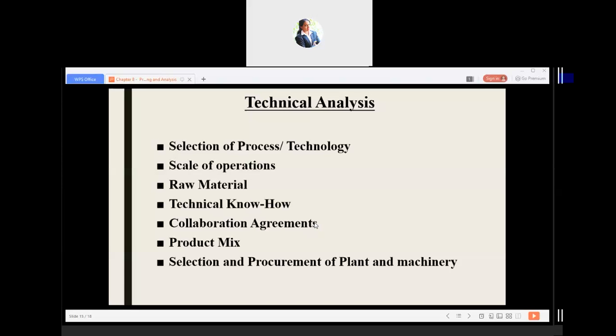Now, the capacity of each machinery is to be decided by making a very rough estimate, by taking into consideration what would be the estimated output, deciding what are the machine hours that would be necessary for each kind of operation, and analyzing the machine capacity after giving necessary allowance for machinery maintenance or breakdowns or the rest time of the workers, the time necessary to set up machines, the time that would be lost during the change of shifts, and other such unavoidable factors of the organization.